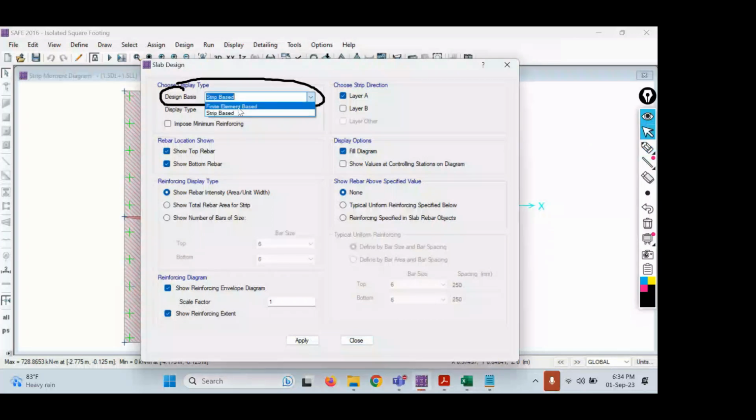Wherever tension happens, we are going to provide the reinforcement in the concrete section to take care of the bending, or flexure. Here, this is enveloping flexural reinforcement, and here we will see the reinforcement later. Okay, we'll talk about the shear reinforcement. If you click on this drop-down, you can see shear reinforcement. We'll talk about shear reinforcement later.